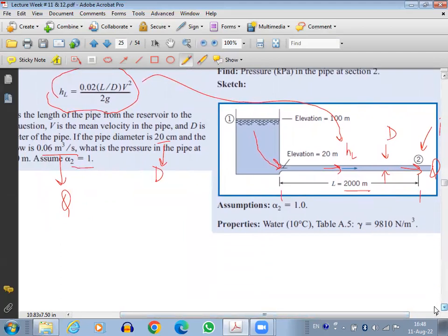How do we know that we have to apply the energy equation? One thing is very clear: whenever the fluid is moving in a pipe, and the pipe has a small diameter, you cannot ignore the viscous effects. You can ignore the viscous effects in this region, but here you cannot ignore them, because it is too close to the pipe. The pipe is stationary, the fluid is moving, so there will be relative motion between the layers of the fluid. Cannot ignore friction, cannot ignore viscous effects.